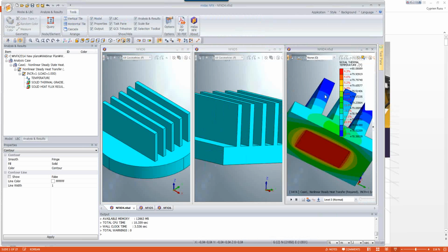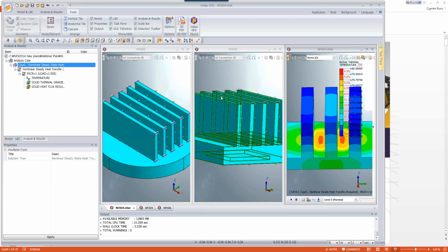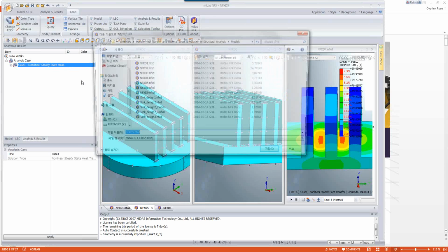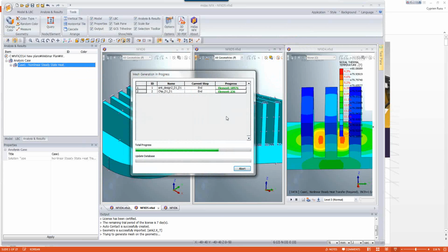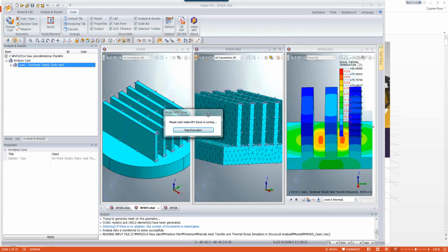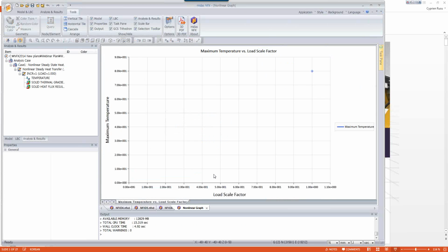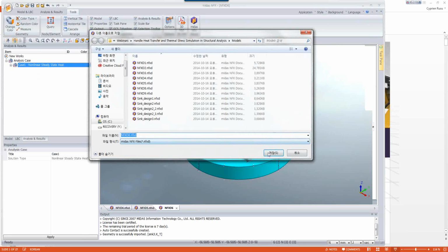So you can see the same model in one window, and you have the analysis I created in this model. So I only have to drag and drop it on the 2 other models like that. And after that, I just click on solve, and you will see it's magic. It's meshed automatically, and then it runs the solver. Okay, finished. So let's do the same with this model.